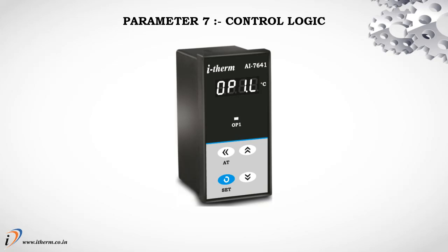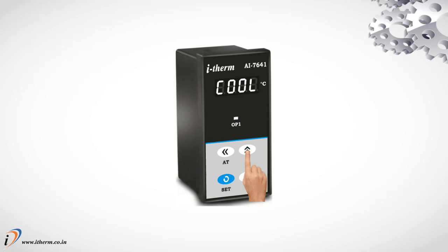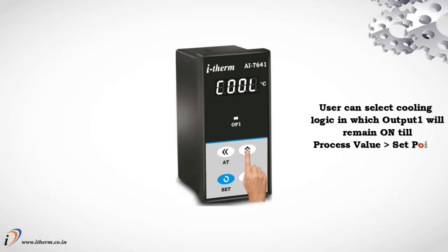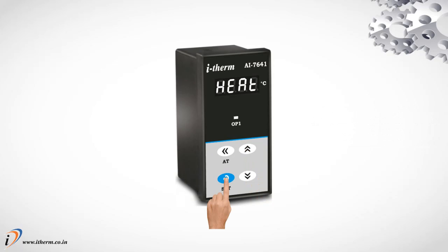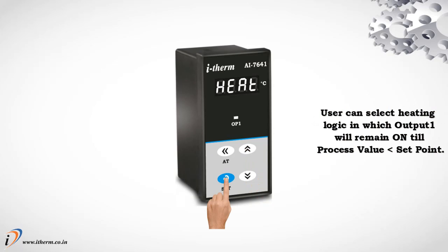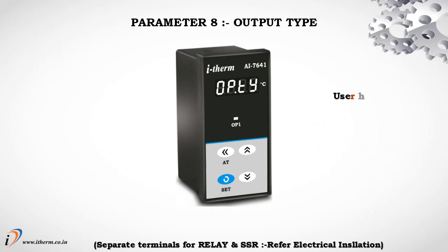Parameter 7, control logic. User can select cooling logic in which output 1 will remain on till the process value is more than the set point. User can select heating logic in which output 1 will remain on till the process value is less than the set point.